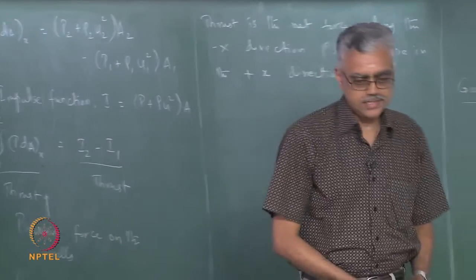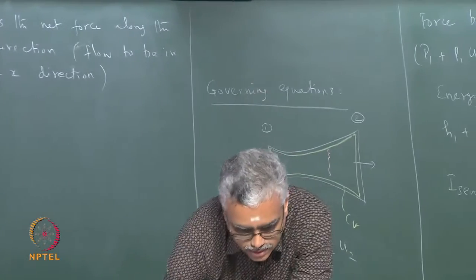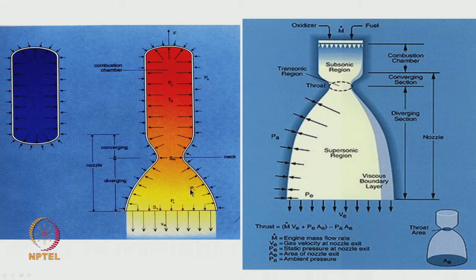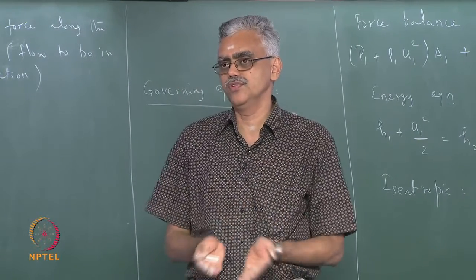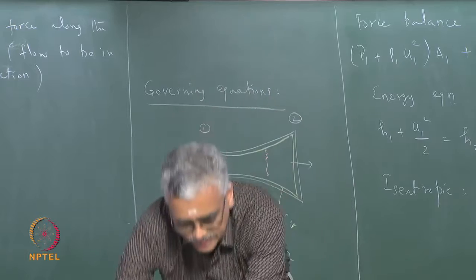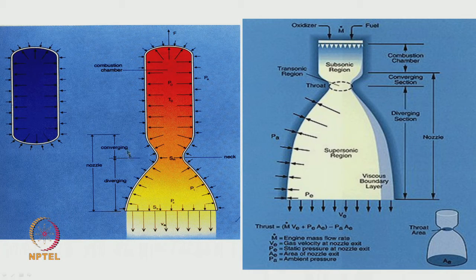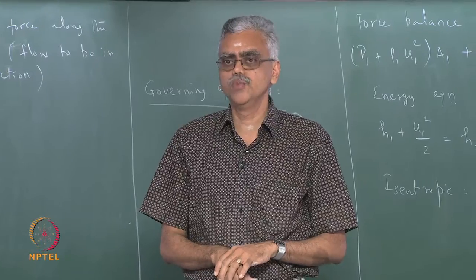Okay. So, you can see that the net unbalanced pressure forces produce thrust, as a result of which the vehicle moves or the airframe moves. I can calculate the force either by integrating the pressure force on the surfaces, so I take this integral, evaluate it along each one of the surfaces, calculate the net force if it is possible, or I can calculate this as I2 minus I1.